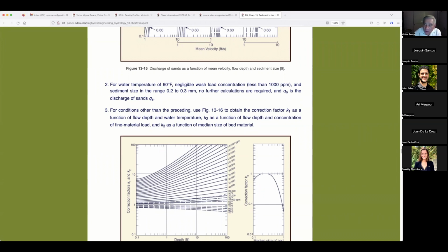Okay, the river looks a little brownish, but for 300, 500, actually clear, more or less clear. But by the time it gets to 1,000, it is already looking like chocolate. And if it gets to 3,000, it will look like latte, coffee, you know. And so 1,000 is not high and is not low. So he used that number for whatever reason, 1,000 ppm. I should tell you that normally the normal background value for this wash load concentration around the world is around 300 to 400 for the wash load.